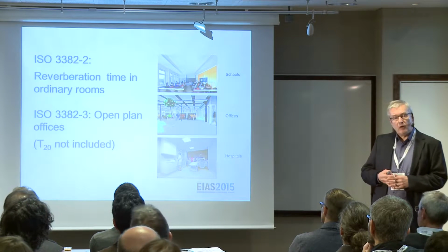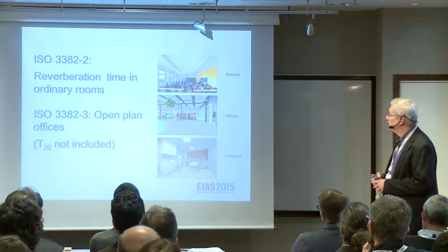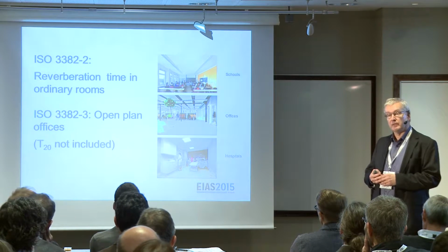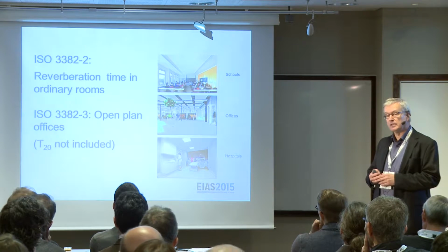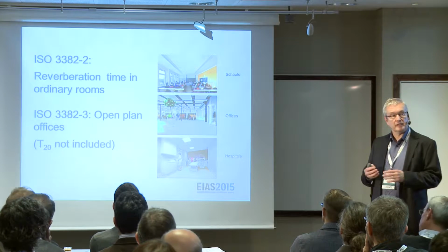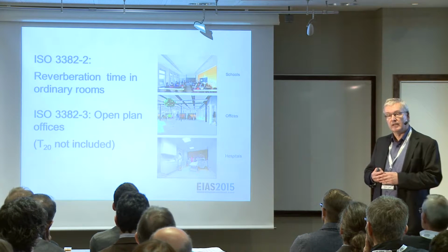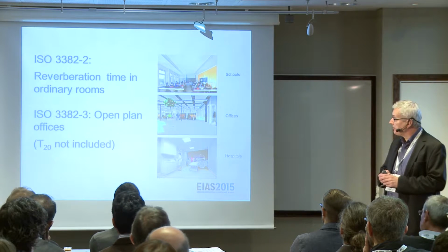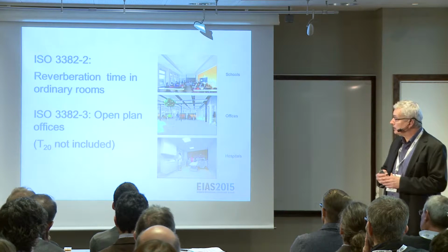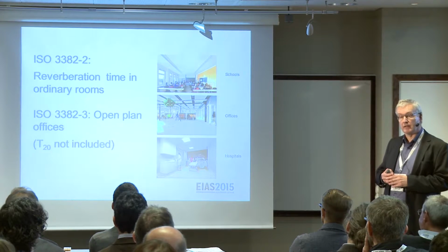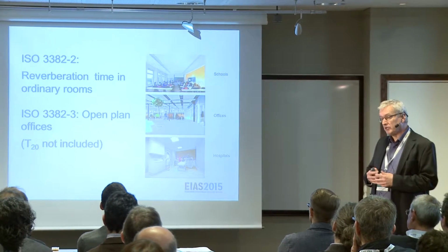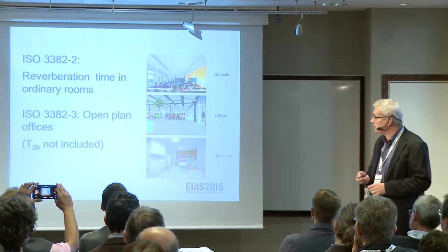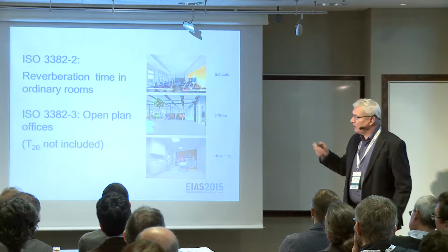But now, if we look at our ordinary rooms, like schools, offices, and hospitals, it's still more about reverberation time. Even though it has been more than 100 years since Sabine's discovery, it's still the dominating parameter in recommendations and standards. There is one exception, and that is the new office standard, where there are other measures. In fact, the reverberation time is not included at all. So that's quite a large difference.